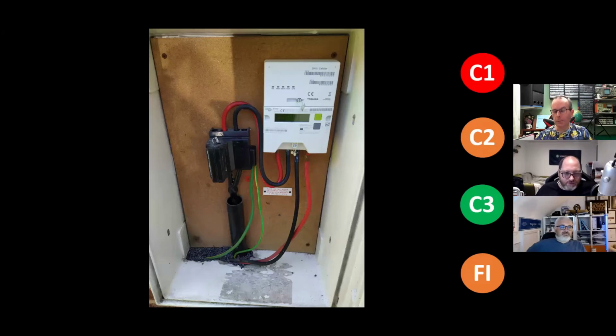Oh, there you go. Okay. Again, it's an older one that had a 6mm when it was fitted, which was compliant. I just stuffed it in there. Do those two conductors fit nicely in that terminal? I didn't look. Probably not, particularly because they're different sizes. I can imagine there's a couple of strand clippings maybe there. Yeah. Well, hey, who's ever heard of reduction lugs?